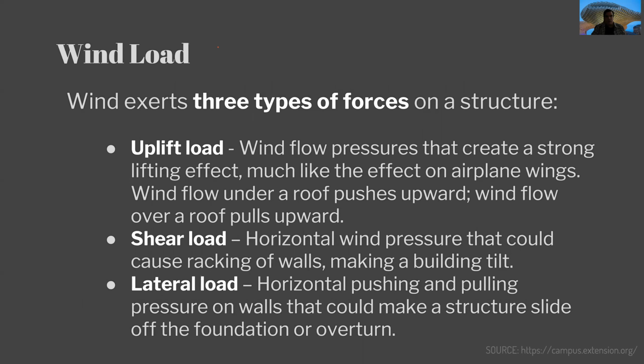The wind will exert three types of forces on a structure. Uplift loads: for example, you will have a roof, and the roof will tend, with the wind, to move up and deform, like in this way.